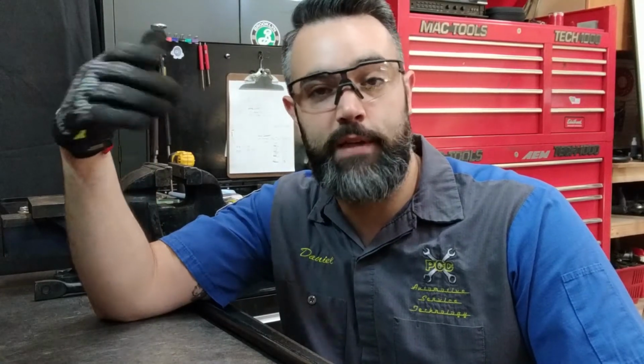Typically, certain criteria need to be met in order for the vehicle to disengage the sway bar. Again, it could be a safety hazard, so it's not going to allow the driver to disengage the sway bar while they're going through S-curves or going down the highway at 50 miles an hour. Typically, it's going to be done under 4 miles an hour, and the vehicle may have to be on a level surface.